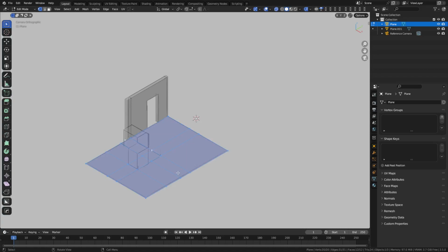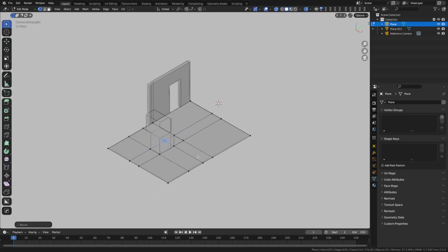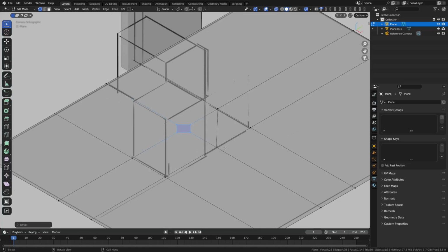But you could say like these two little vertices here, I can press J and join them. This one I can press Control B and V and chamfer it a little bit. So you can see Control B, V to bevel that vertex. Or Shift, is it Shift Control B? Yeah, Shift Control B will work as well. And so this comes out just a little bit here, right here.